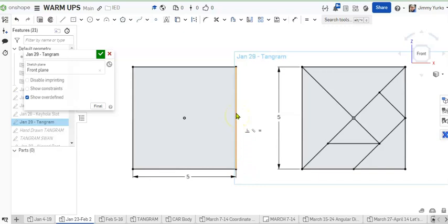The next thing I'm going to do is get the line tool, L, from the tool ribbon. I'm going to draw a diagonal line from the lower left-hand side of the rectangle all the way to the upper right-hand corner. You can see that it passes through the origin. In order to make later steps easier, I'm going to make a pit stop at the origin, so that instead of having a single line, I actually have 2 line segments. While we're at it, we're going to draw a diagonal line from the upper left back to the origin.